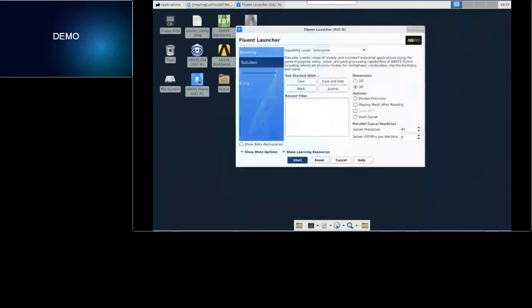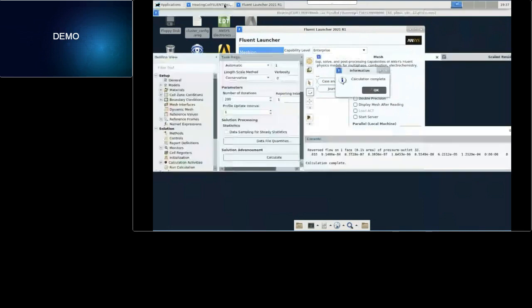And there are our different Ansys applications listed out there, whether it's Fluent, Workbench, Electronics Desktop, FENSAP, CFX. They're all installed and available. We're going to use Fluent. So we quite literally can just double-click, set the number of processors, our case and data files, as well as our licensing capability, and we're ready to go. Now, again, in the interest of time, I've already started Fluent up for us with this same model.